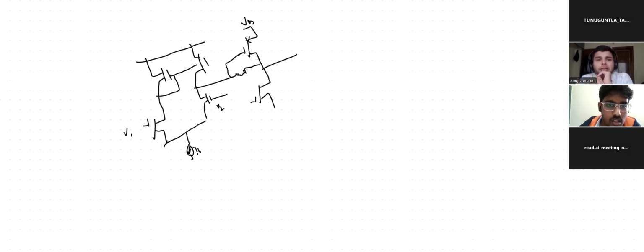So you used Miller compensation. Yes. And also here we have given a common drain for making the output impedance zero. This is a simple common drain amplifier. So what were you driving here? What load? We didn't keep any load here. It's just a capacitor of 1 picofarad.